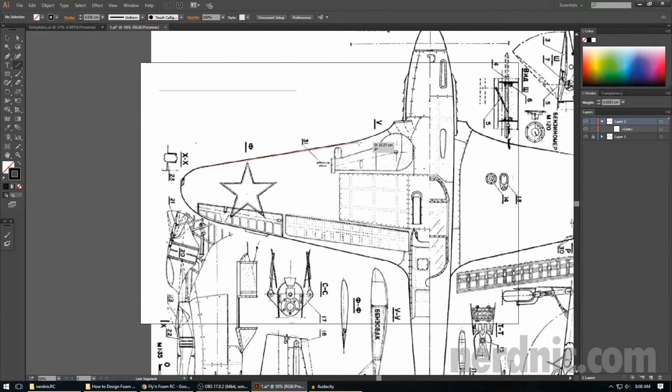Now, if you'll notice, this has a weird curve in the leading edge, and this is actually not possible to accomplish on foam board as a foldover as one piece. You have to come back and add this as a second piece. So this part that curves here is going to have to come as an attachment, right? So for this, if you have a plane that has a bend like this, leading forward, then just skip it. You want to actually grab your line.